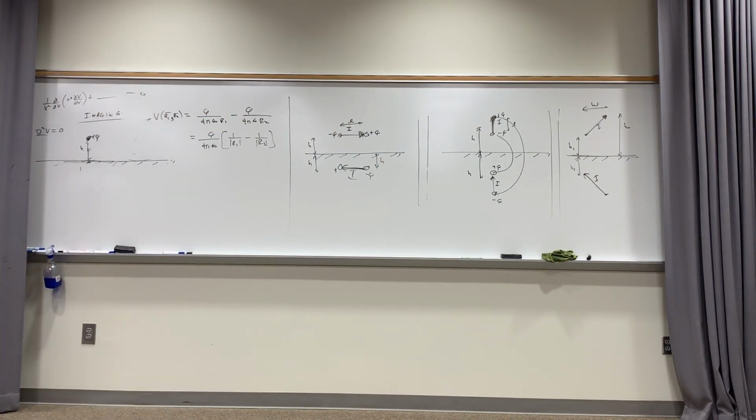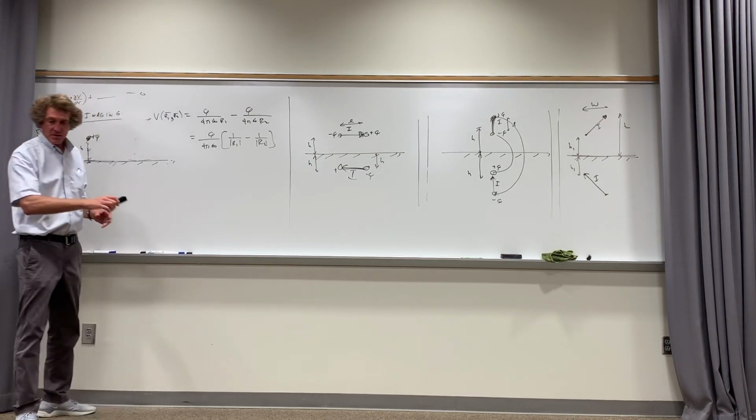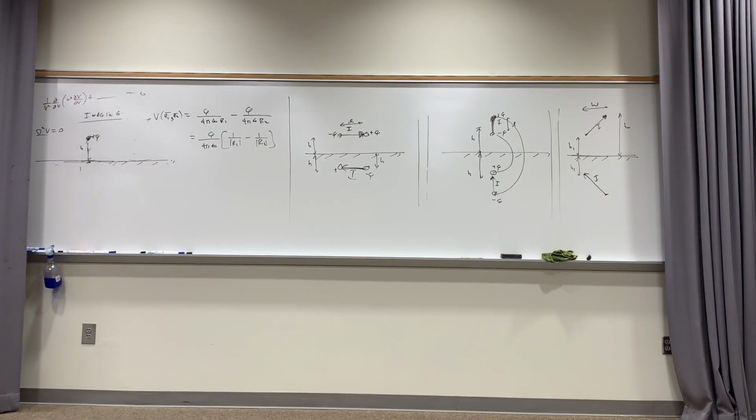So now we look at some typical examples, and this is done all the time. These are how monopoles are really created and used. Anytime you have a large conducting surface, or even sometimes not a large conducting surface, like the aerial on the old car antennas, it's not a dipole that folds out and has a center feed with something down and something up, and then it's driven. It's just an aerial straight up from your car, right? But your car's conducting, usually. So they use that conducting surface as a ground plane, and it causes a pseudo-dipole effect. So it looks like a monopole, but not quite. It's still useful.